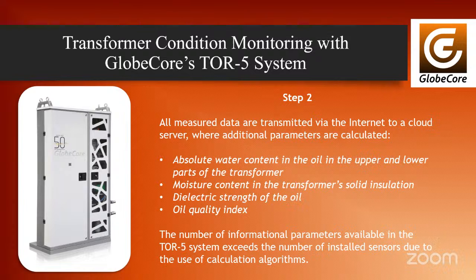On the cloud server, smart algorithms calculate extra diagnostic values to give a better picture of the transformer's health. Moisture in oil, top and bottom, moisture in insulation paper, top and bottom, oil dielectric strength, and oil quality index, OQI. These models make it possible to get more diagnostic values than the number of real sensors installed. The system goes beyond simple moisture measurement and shows deeper reads for oil and insulation.